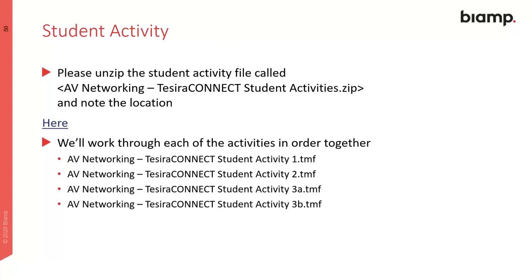Another thing is that the Dante protocol uses PTP version 1, whereas the AVB protocol uses PTP version 2. And for AVB, all devices need to be AVB aware. Not just the end devices like the DSP and the expander, even the switch network fabric has to be AVB capable. In the case of Dante, it's more agnostic.